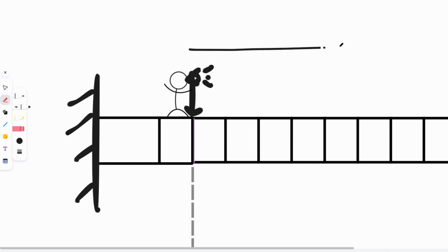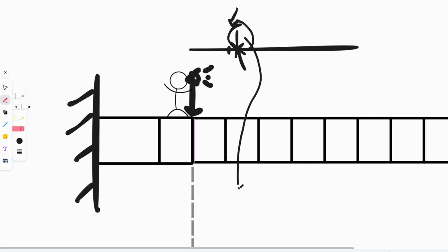Many people get confused when they draw this beam like this, for example, and this is the shear force, right? And they are observing it from this point and then coming here to here to here to this point itself. They get confused as to whether this shear force is trying to move the right side downwards or is it trying to move the left side downwards, right? And the mistake that they make is they try to analyze it from this point itself, right? They try to observe this force from the point on which the force is acting. That is not the right concept. You will have to move to the left of this force for this force to be reflected in the shear force diagram.